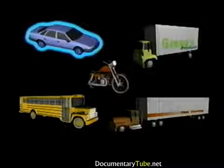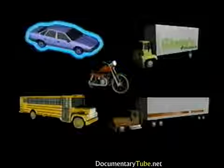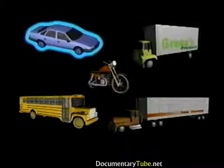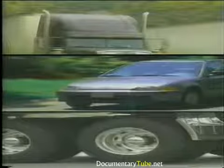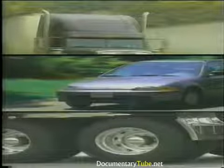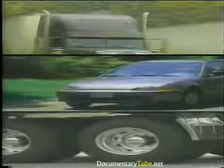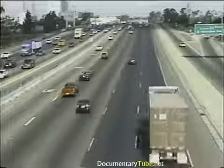For the same conditions as the example heavy truck, the maximum sound level of the automobile is around 75 dBA. The major noise sources in vehicles are, for trucks, the exhaust stack, and for all vehicles, the engine and tire-pavement interaction. The sound levels of individual vehicle noise are influenced by how fast the vehicle is traveling.